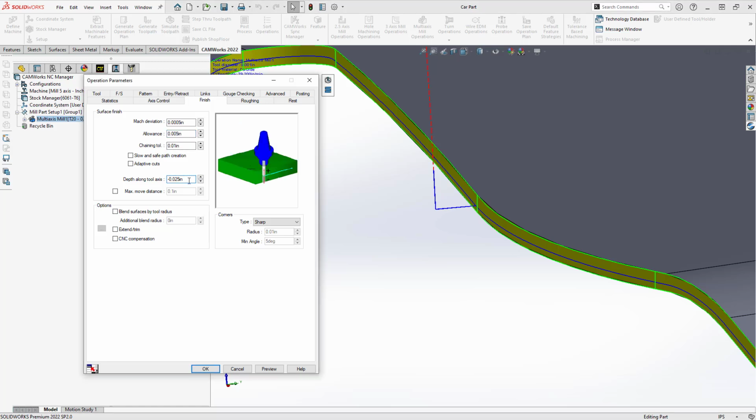And you'll notice the numbers are a little different, and that's because even though we're trying to gouge the part, we still need to kind of control exactly how much we want to go down to achieve the amount of chamfer we're looking for. And the numbers are very simple to calculate. So in this case, I'm giving it a 5 thou allowance. I want a 20 thou chamfer, so that means I just need to drop it by that 5 thou and the 20 thou, because again, if I just made these numbers similar, I'm just going to be moving along that tapered wall.